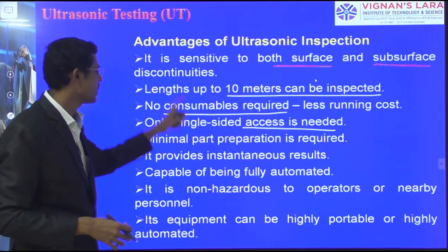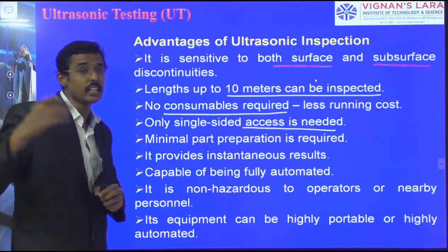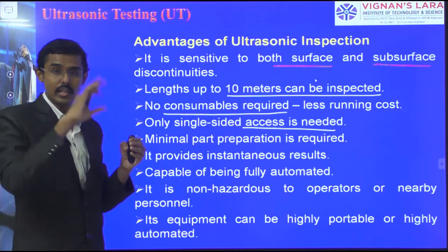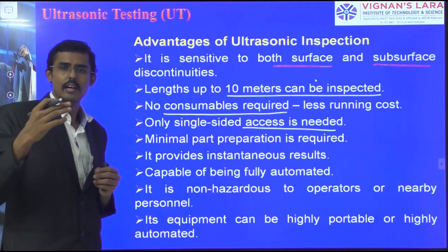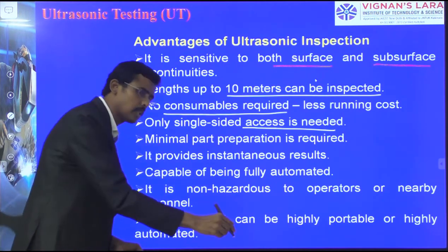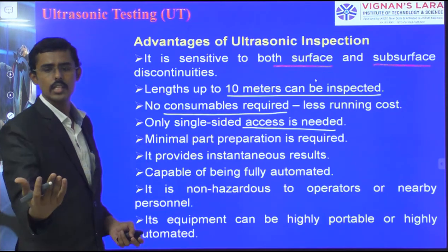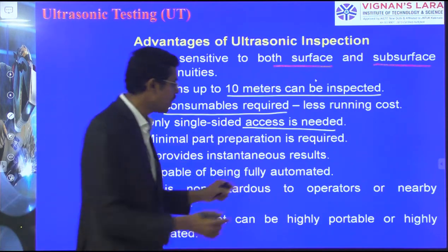It provides instantaneous results. We see them immediately on the CRT screen. But in radiography, we have to clean, dry, and then only it is possible, taking at least 5 to 8 hours. But here, the moment you keep the probe on the specimen, we see the result on the CRT screen. So it is very easy. It can also be fully automated.